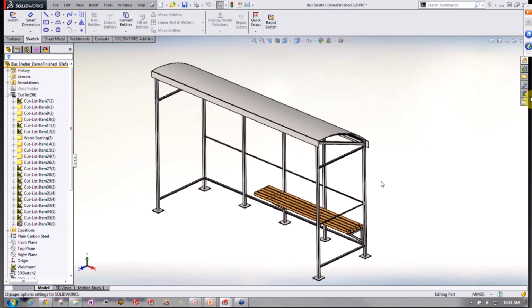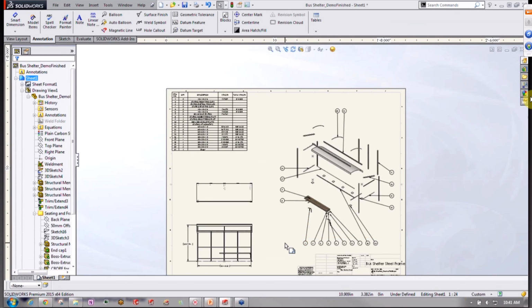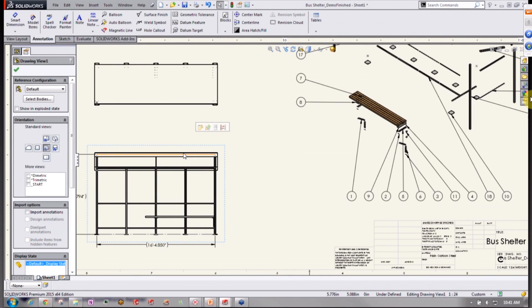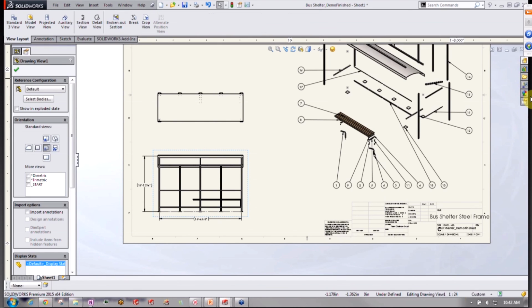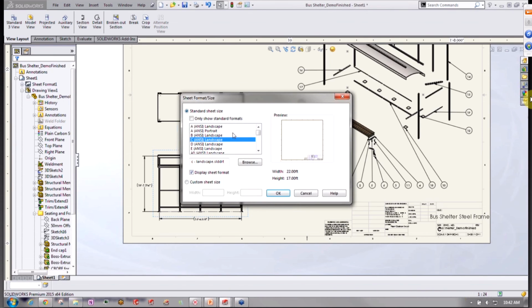And can you create drawings for individual weldment components? Yes, you can. There are different workflows for that. So if we're looking at this drawing, what I would typically end up doing is inserting a new view. Maybe I make a new sheet even. Okay, make a new drawing sheet, choose the template I want to be using.